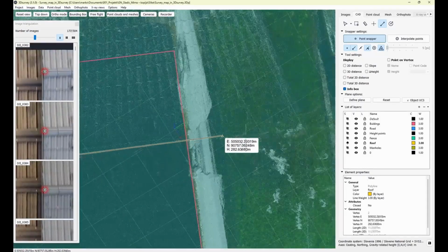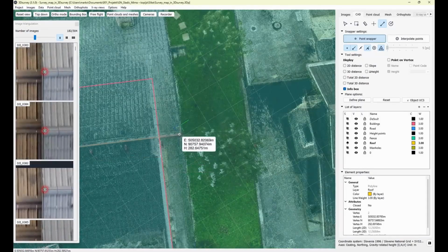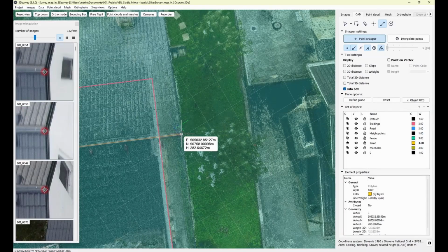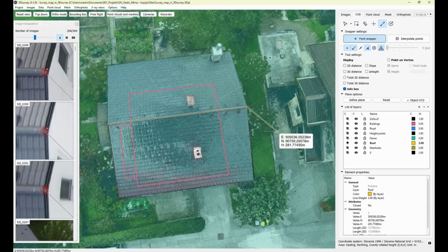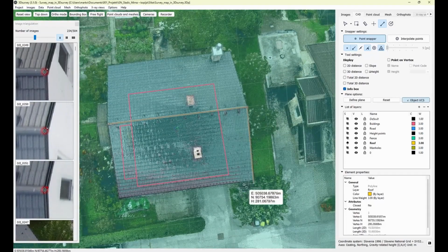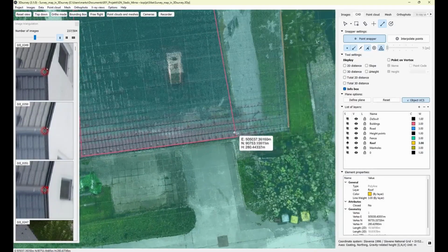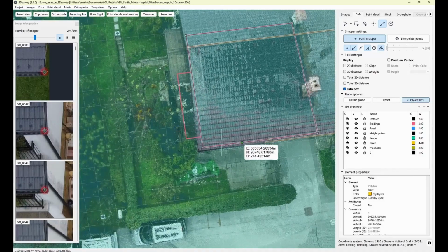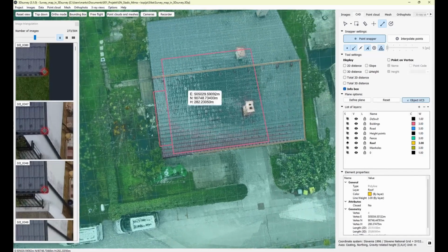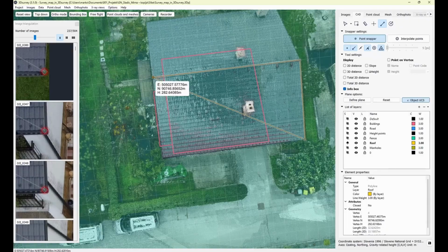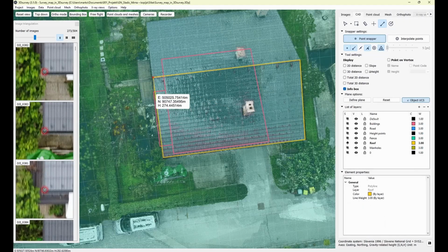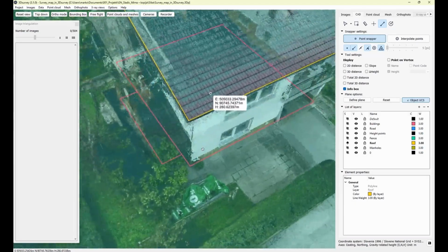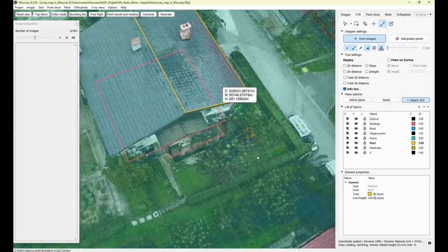What I need to do is extract my first line like that, improve it on a point, then press the F8 button again to align it, and now I can draw like that, so I can even see clearly where it is. And again, if I like, I activate my snapper, the last one, and then I get suggestions with the green line. It should end somewhere here, like that. And you see, this is a perfect match for my roof.